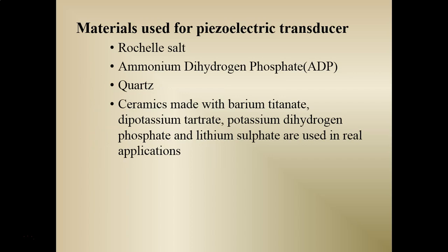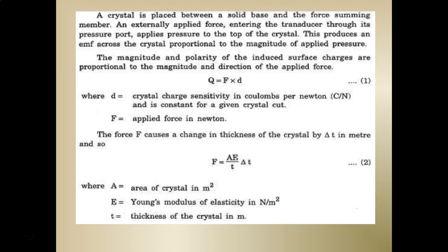The materials used for piezoelectric transducers are Rochelle salt, ammonium dihydrogen phosphate, quartz, ceramics made with barium titanate, dipotassium tartrate, potassium dihydrogen phosphate, and lithium sulfate. The magnitude and polarity of the induced surface charges are proportional to the magnitude and direction of the applied force. So the charge is given by F into D, where F is the applied force in Newtons and D is the crystal charge sensitivity in coulombs per Newton.